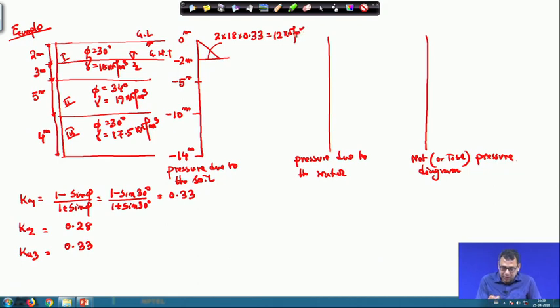Okay. Now, below the water table this 12 kilonewton per meter square pressure will continue. Okay. Because that will act as a surcharge for the portion below the water table and as the K value is the same, it will continue like this in this zone. Okay. And then there will be more pressure due to the soil. Okay. So, this portion is the pressure due to the soil.